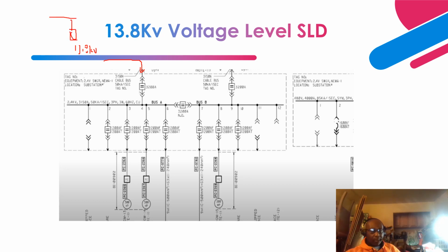With a breaker, then it comes from here. Or it could come from a transformer that steps the voltage down, let's say from 69 kV or 115 kV to 13.8 kV level before it comes in here. So when it comes in here, this is an incomer breaker.